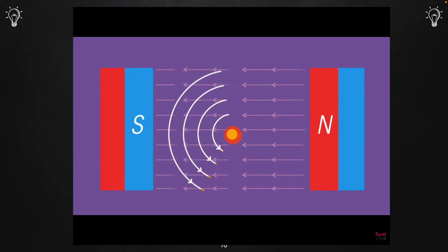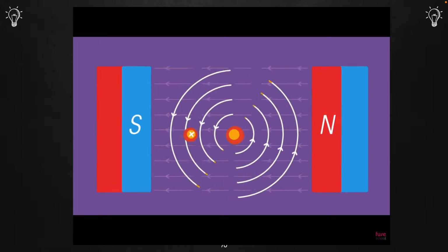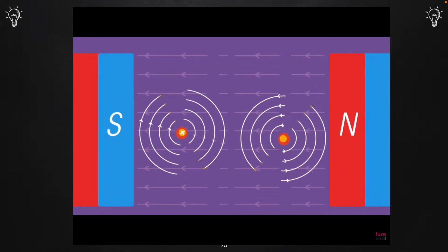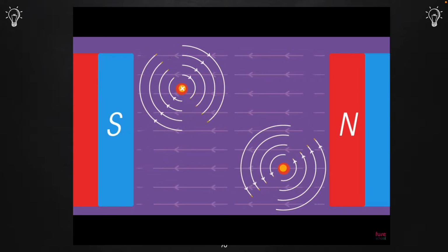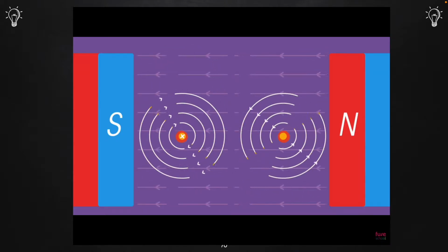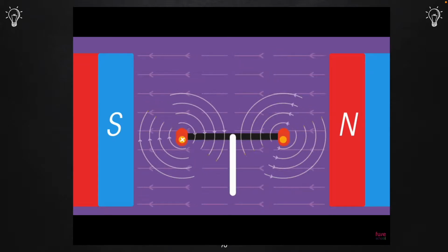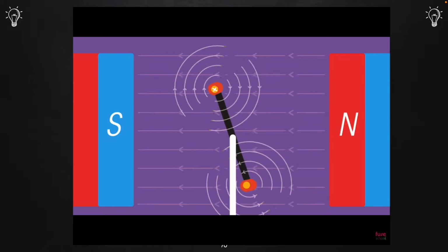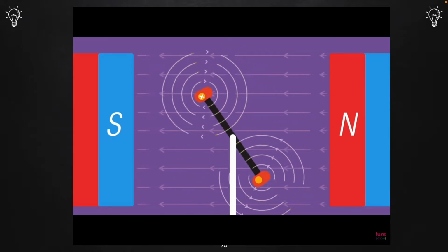Now, reverse the current. This experiences a force in the opposite direction. Now, place both wires in the same field. One wire will be pushed up, the other down, but we don't have circular motion yet. Now, if we link the wires together and then insert a spindle to allow a rotation, we convert the opposing up-down motion into a rotation, and here you have an electric motor.